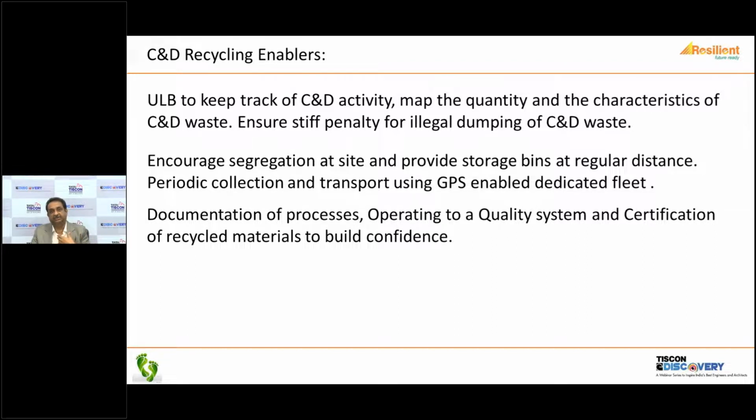problems for the structures. And this is why I said, because you have concrete and material coming from multiple different sources, it's always difficult to actually use the material without knowing its origin. So it's important that there is a documentation process in place, a good quality system in place, and a certification program which actually encourages people to use these recycled aggregates.